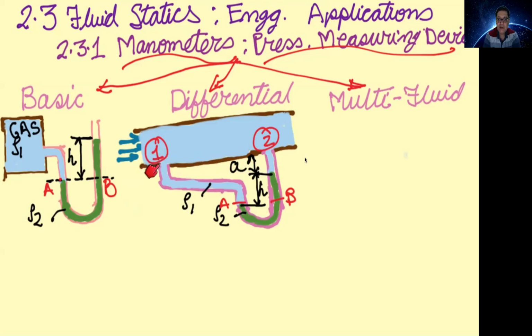So in this U-tube manometer, where the manometric fluid is this green fluid, since there is a larger pressure here, the fluid will move to a larger depth as compared to the fluid here. That way you end up with a height difference of the manometric fluid, which is represented here by h. And A is the distance between this pipe or channel and this location.